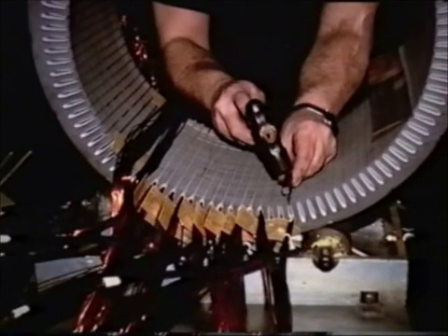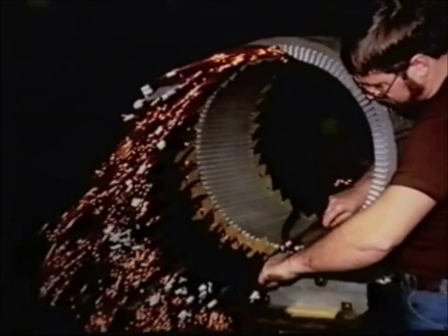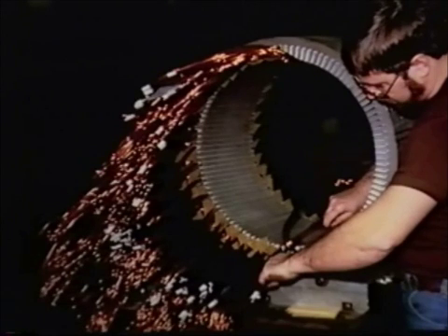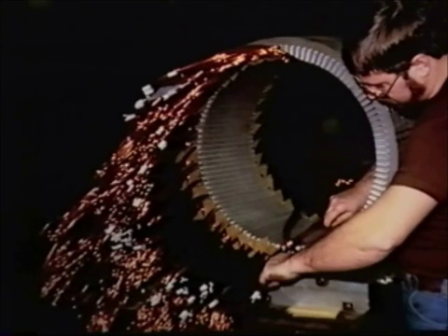Following a diagram, the winder places the individual coils comprising the winding into the core slots with various insulating materials. Once the coils are inserted in the slots, the individual coil ends, referred to as the start and finish wires, are grouped together according to the specific instructions, and the load leads are then connected.